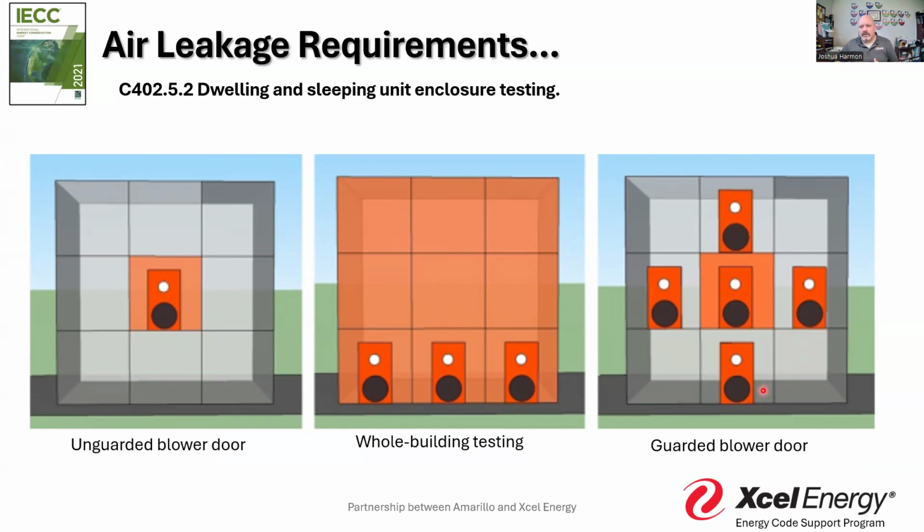So that way, if I'm in the room and there's nobody around me, I don't have to have it kicked up to 75 to get it to 68, because there's so much air leakage going on around me that I can't maintain a reasonable temperature. This is the blower door that we normally see performed and associated with this type of work.